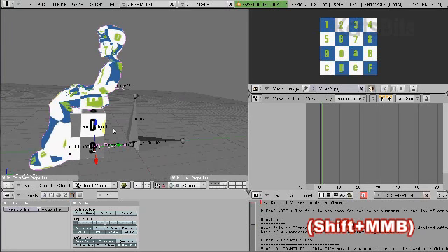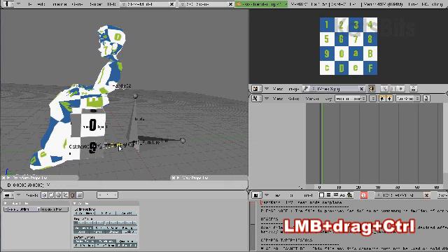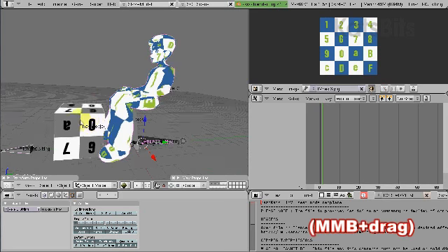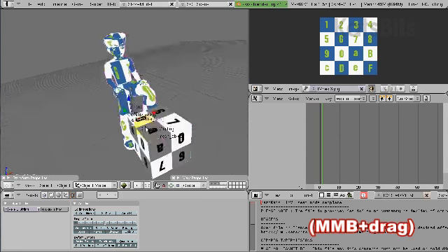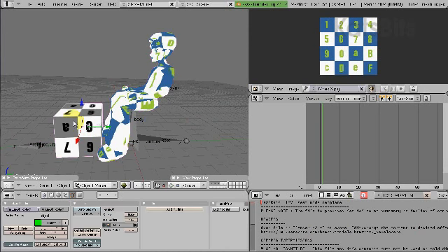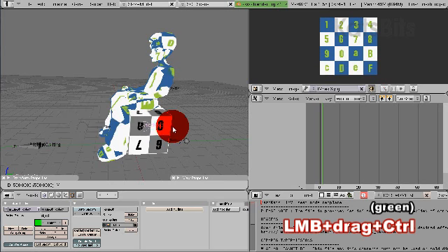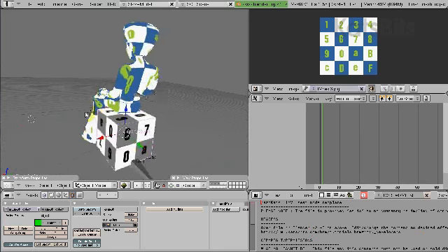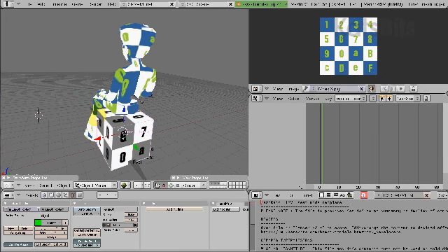Rotate around, do the same thing again, this time with the green handle, hold Control and centralize it. We'll use this as a positional device relative to the chair. If we now select the cube by right clicking it, same thing again, the green handle, hold Control and move that into place. From this, we've got the basics of our block chair.